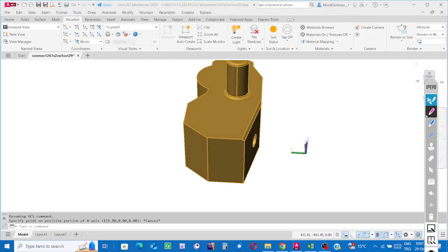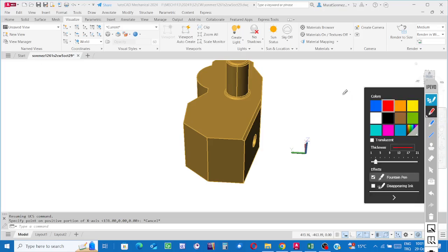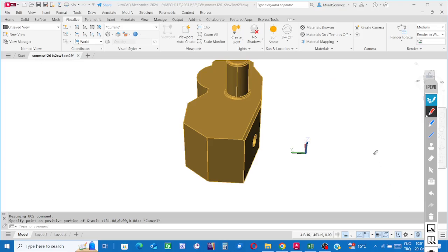Dear students, in engineering drawing, to mark the points, we use a tilted cross, not a dot, but a tilted cross. Because in engineering drawing, a dot means the projection of a tiny cylindrical feature. To say that it is a marker, a point, we use the tilted cross. Although it is under common agreement, in the default configuration of AutoCAD, the point marker is a dot.